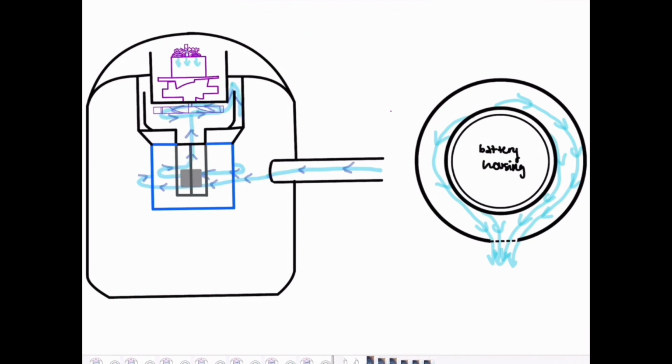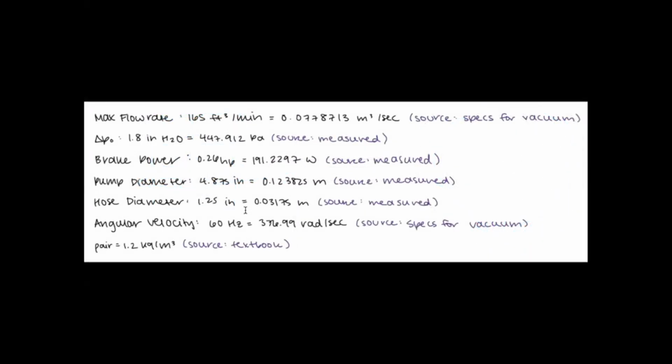the outlet channel. Bernoulli's equation with losses cannot be applied to the flow across the radial fan due to the aforementioned pressure discontinuity. Inside the outlet channel, the flow experiences a higher pressure that is greater than the atmospheric pressure. This pressure gradient encourages flow to move through the outlet channel to the exhaust outlet and out into the atmosphere at atmospheric pressure. In order to characterize the pump, we can calculate non-dimensionalized parameters to show how they depend on the pump diameter and pump speed.